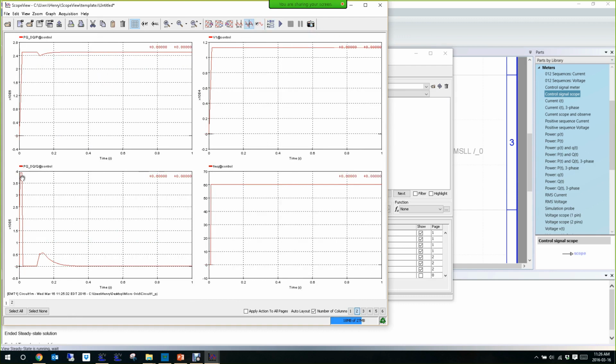So at the beginning, we start the power meter. As you know, they take 1 cycle to identify the real power. So the first 20 milliseconds, or 16 milliseconds really, are not to be considered. But you see after we have the good power and 0 for the reactive power. Here we have a small transient. Okay, I will discuss that right after.